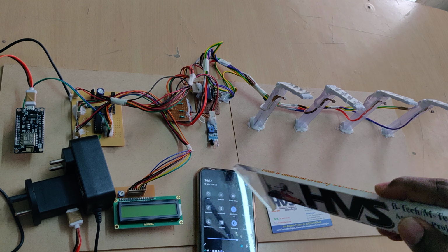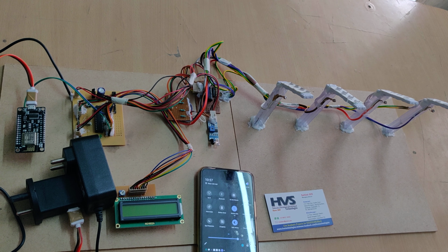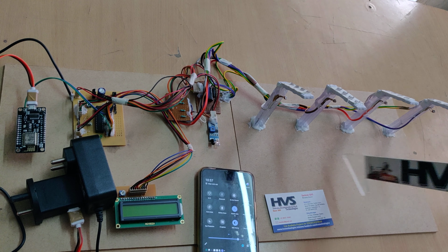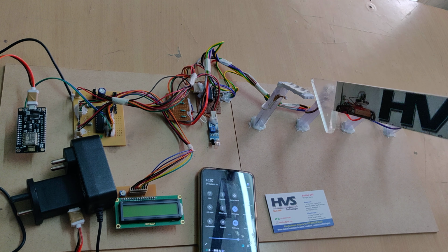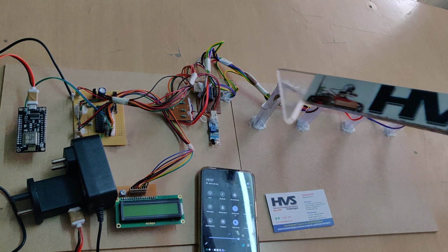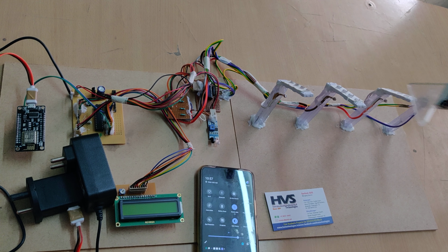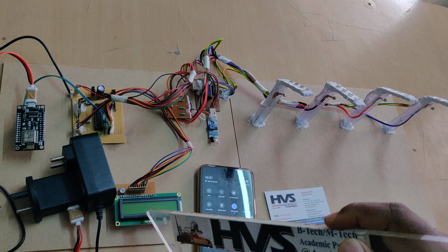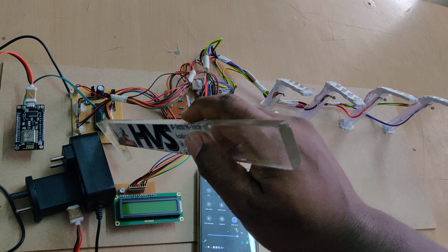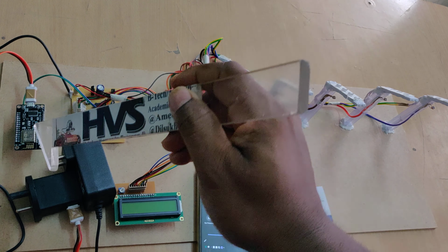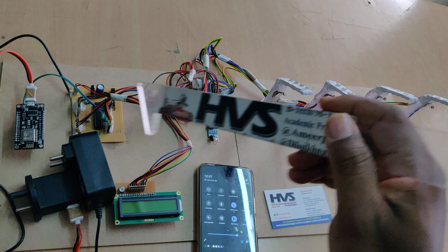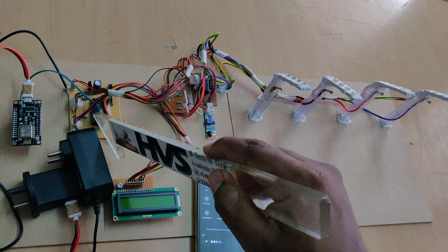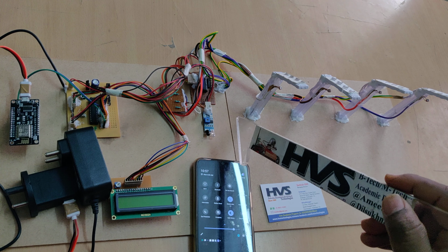So here we are going to control the whole system based on input and output modules. The inputs are IR sensors and an LDR sensor for each street light, and the output modules are the LCD, the Node MCU and the street lights. These street lights are controlled with the help of ULN 2803, and the LCD interfaces with a PIC microcontroller. As there are insufficient pins on the Node MCU, we are using an extra driver, a microcontroller, which interfaces between the Node MCU and the input and output modules.